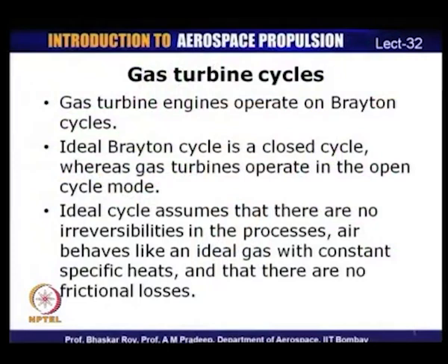At the same time, you get some idea of the performance of a cycle if it were to operate in an ideal mode, and therefore, it is a starting point for designers. An ideal cycle really helps in understanding the thermodynamic cycle. So, when we talk about the Brayton cycle, the ideal Brayton cycle is a closed cycle, but gas turbines operate in an open cycle mode, but of course, they can be modeled using air standard assumptions.